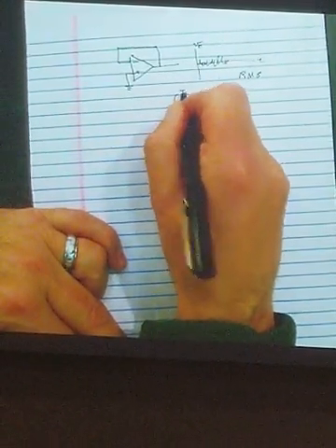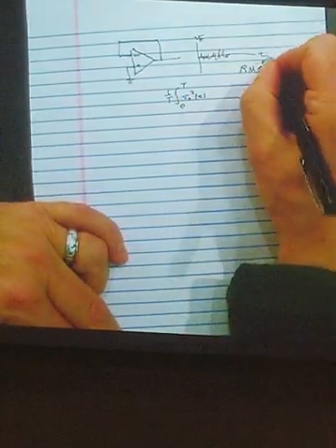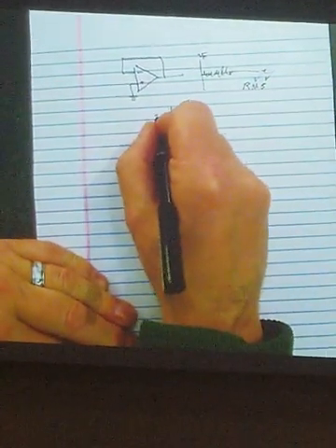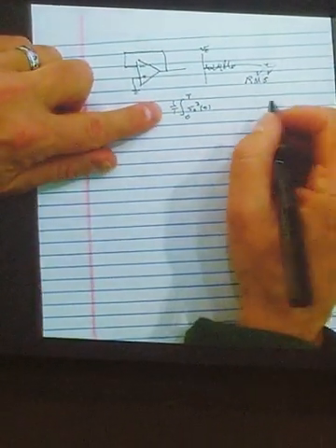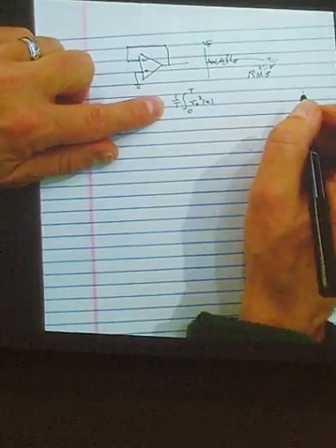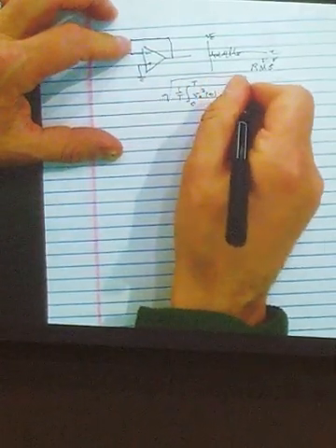As long as it takes, and we would average it. So square, there's the mean, and then actually we could just stop there, and that's the mean square voltage. Or we can take the square root of the whole thing, and that's a voltage in RMS.